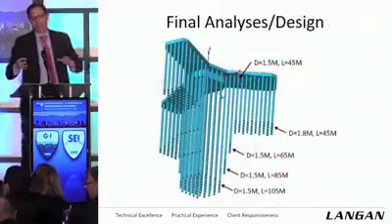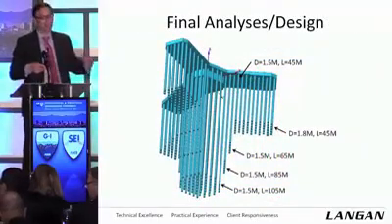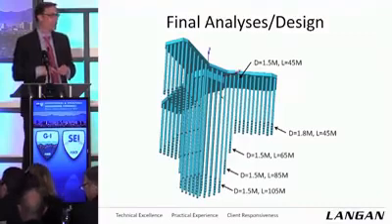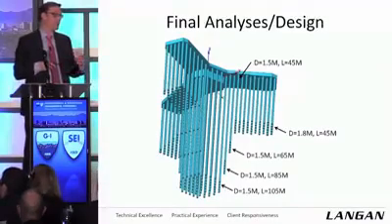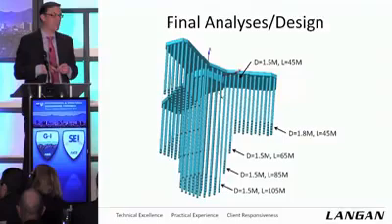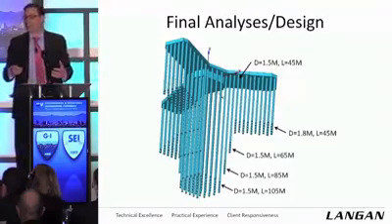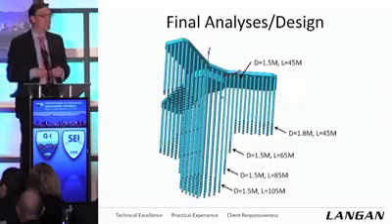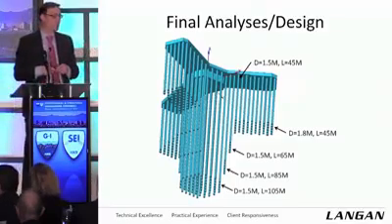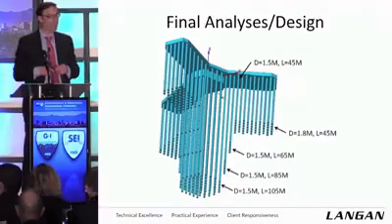So again, we looked at it from another perspective and said, all right, what we really need to do is control differential settlements and control total settlements of the center of the tower. And we can't stuff any more piles into this thing. It's already 2.5 D on center. So of course the solution was to take the piles in the center of the tower deeper.